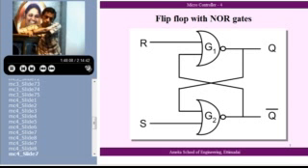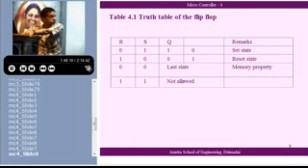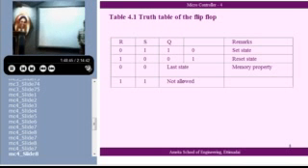If you give 0, 0, what was there? It will be there. What was the previous value? If you give 0, 1, that's a unique output. If I give 0, 1 as input, Q will go 1. If you give 1, 0, Q will go to 0, that is unique. But if you make both of them 0, 0, whatever is the previous state, that is retained. It is not unique. Do you understand? If it is 0, 0, output can be 1, 0 or 0, 1.